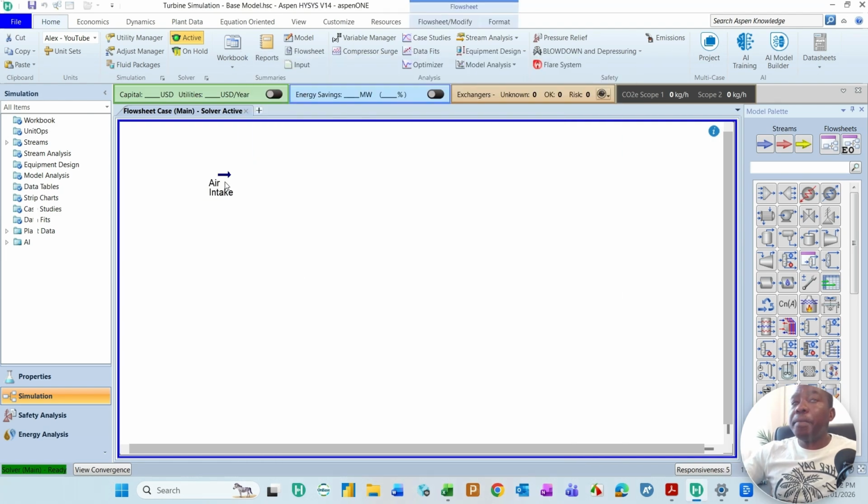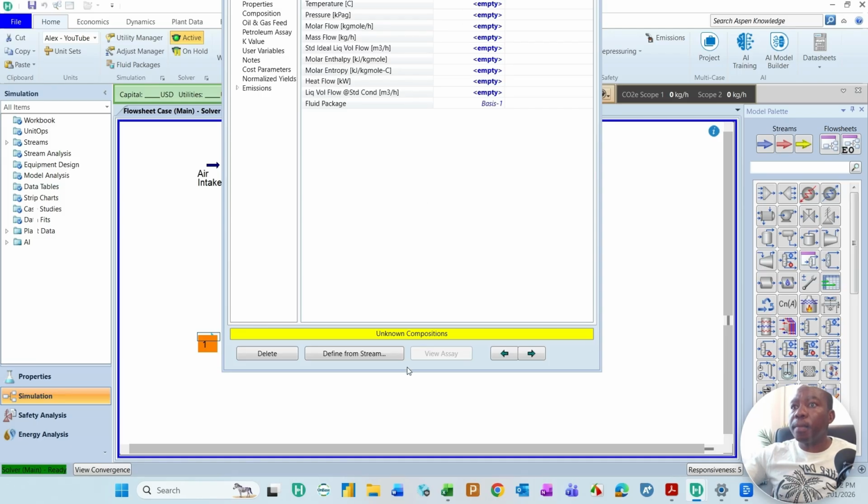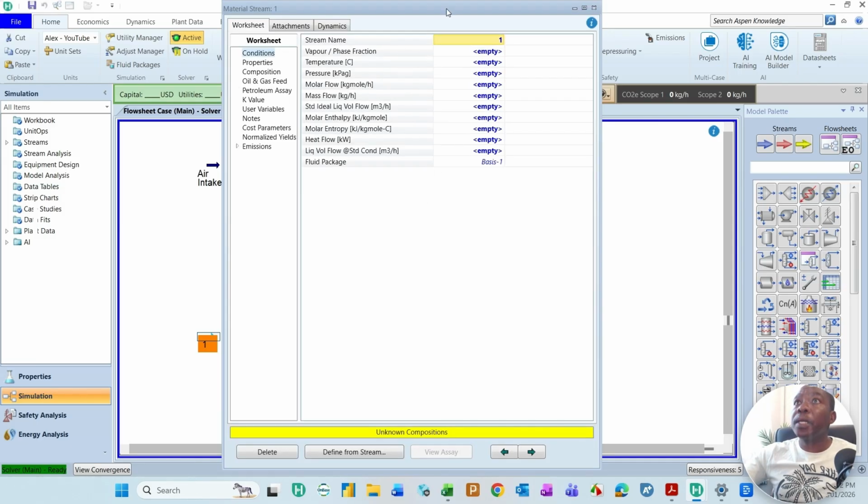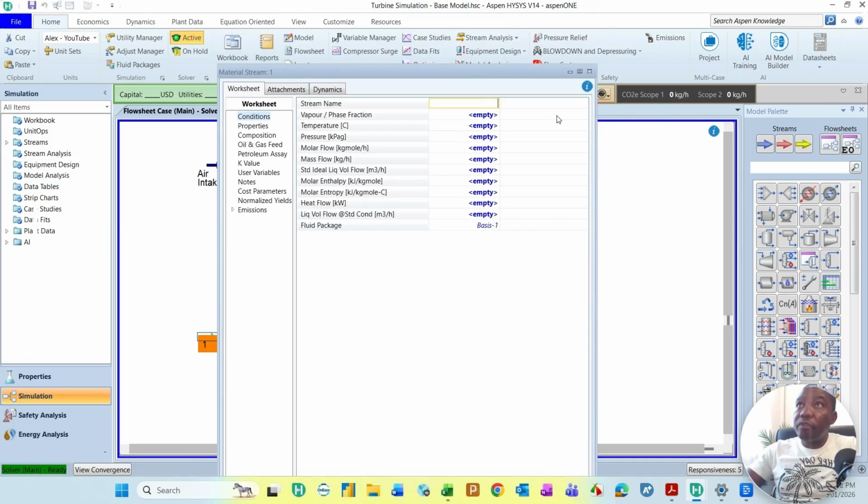The second step is to insert your fuel gas, right? This is going to be a little bit interesting. I'll show you what you need to be careful of in this one here. We're going to rename that to fuel gas. Call this battery limit fuel gas. So this fuel gas is still coming from the supplier. It's just coming in at our battery limit.